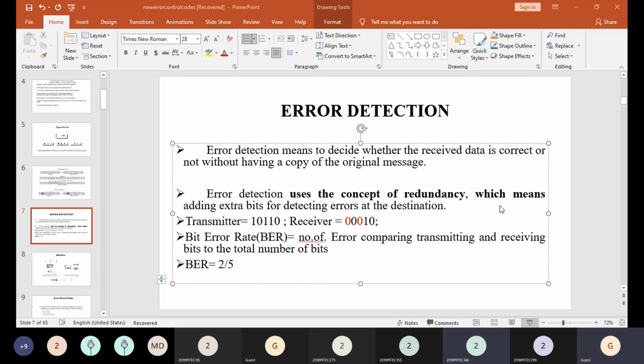The checking uses the polynomials in the decoder, and then you need to find out once again what the information bits or the data which was transmitted and received are. Now we'll go on to the first possibility, linear block codes. You see here k bits are taken as inputs. If it is an (n, k) linear block code, k bits are taken as input.